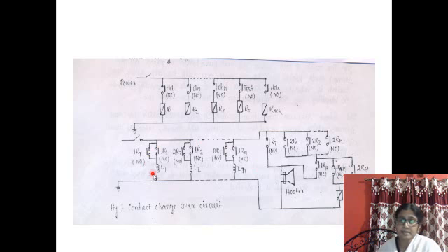If this is corrected externally, that means using reset switch, then there must be another contact of reset, and otherwise if there exists ring back sequence, then after correction that will be taken automatically. That means there must exist another switch to turn off the lamps. So this is what about the lamps and audio, that means visual and audio signals.